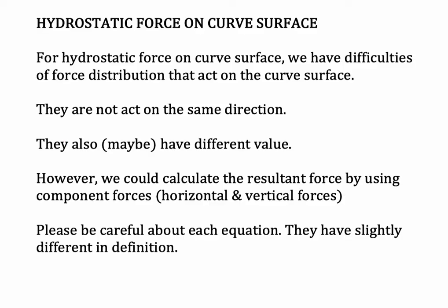Hydrostatic force on curved surface. For hydrostatic force on a curved surface, we have difficulties with the force distribution that acts on the curved surface. The forces do not act in the same direction, and they also have different values. However, we can calculate the resultant force by using component forces, which we call the horizontal and vertical force. Please be careful about each equation. They have slightly different definitions.